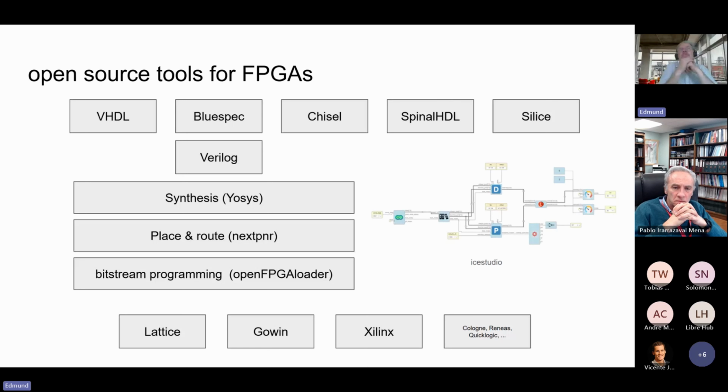When you write a hardware design in Verilog, you have to understand how Verilog designs have to be designed, have to be verified, have to be simulated, and it's a rather low-level language. And for this, there are other front ends to Yosys, where tools like BlueSpec or Chisel or SpinalHDL, those are different languages, but they generate as output a Verilog file, which then can be again used in Yosys.